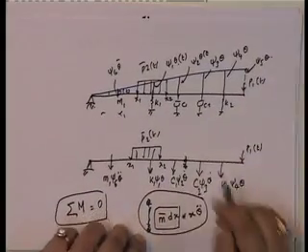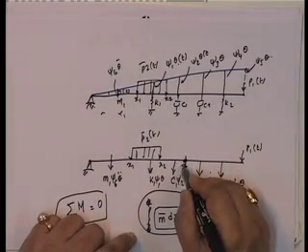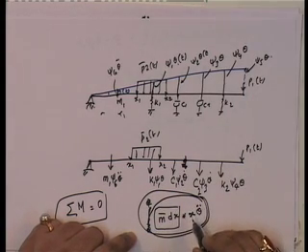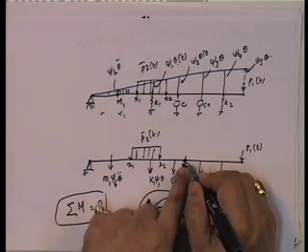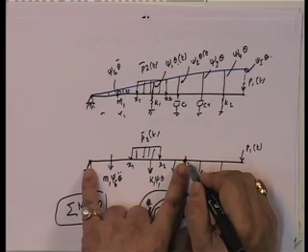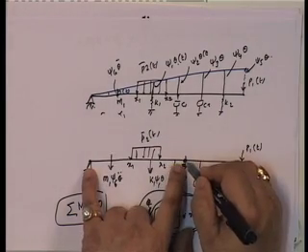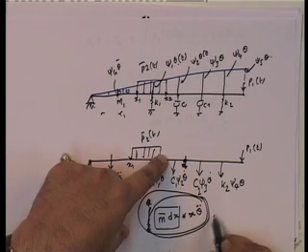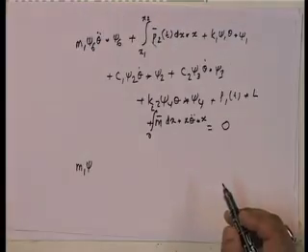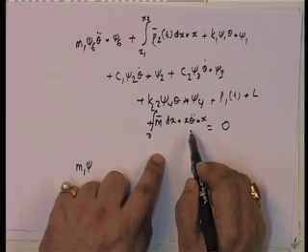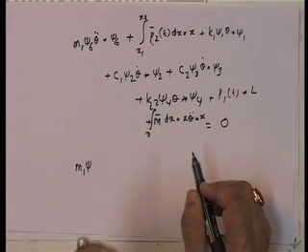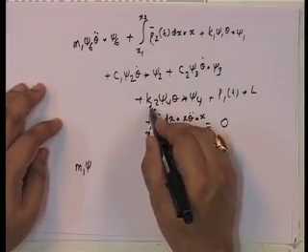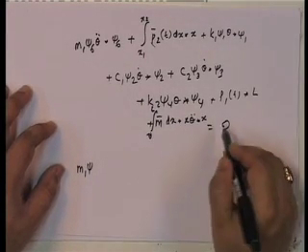Look, I have taken an infinitesimal mass. If you look back at this, I have taken an infinitesimal mass at length x, and found out that this was the inertial force. So, this inertial force, if I take this infinitesimal inertial force, this is length x. So, what is the moment about this point? Moment about this point is going to be m bar dx into x theta multiplied by x. So, that is what you have, m bar x, but note that is the infinitesimal length, that is the mass for a particular infinitesimal length. Now, this mass exists all across. So, this would have been 0 to L, and this is equal to 0.